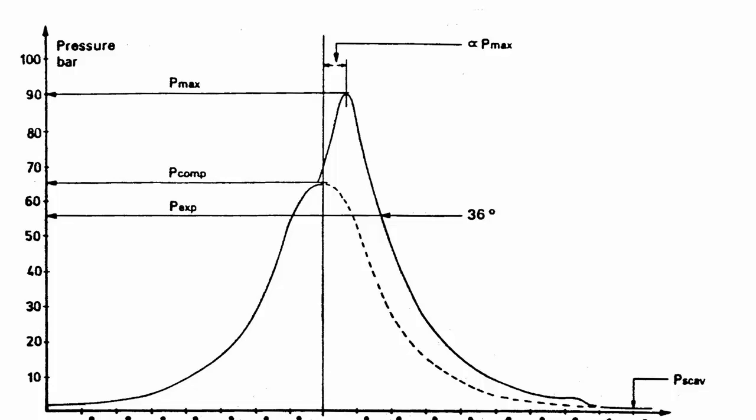If you're talking about an engine such as used on the roadways in the United States that's burning a clean distillate, and specifically what we would call in the marine industry marine gas oil, what shoreside is known as number 2 diesel, the ignition delay for those fuels is a standard, and it will not change. It's about 10 milliseconds. So in other words, when you inject fuel into the cylinder, it will atomize and then ignite in about 10 milliseconds.